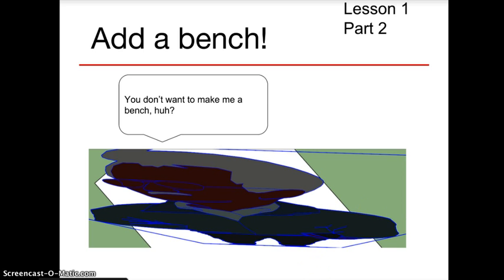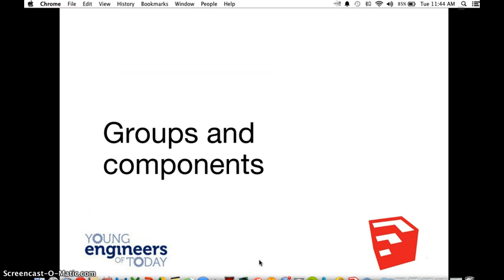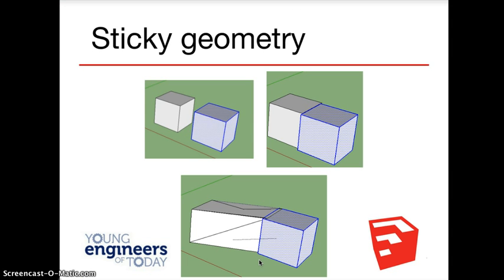All right, and I will go through a little bit of yesterday as well. Now this leads us to groups and components. Once again, this is presentation 2. We've gone over presentation 1 part 2, and presentation 2. We'll start here. All right, sticky geometry. Be careful aligning faces with multiple shapes, because they will end up attaching to themselves, and when you go to move them, it gets awkward.